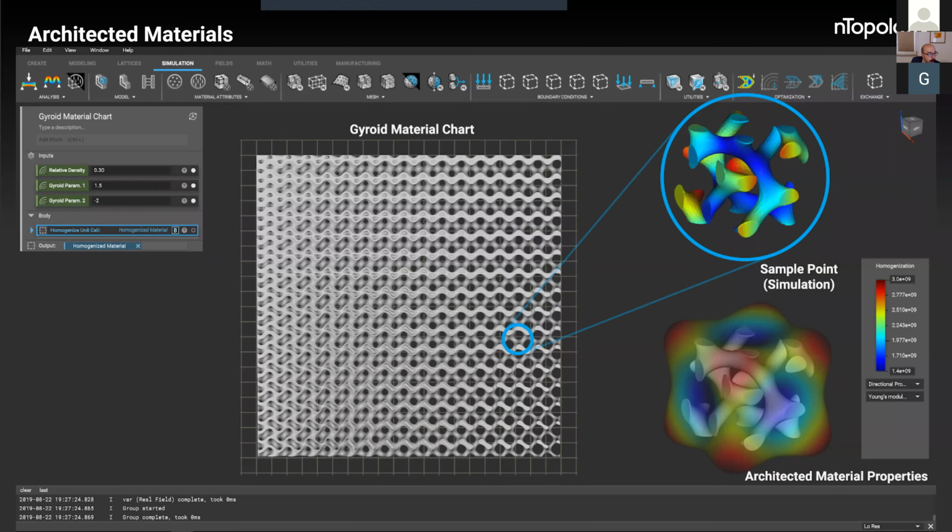All right, can the lattice structures also be exported in step format for further native CAD editing? Good question. So I would recommend exporting out lattice structures in 3MF file format rather than a step file format, right? If we think about traditional BREP-based modeling tools, there's a reason that you typically can't create BREP lattices. I've heard from a lot of folks, they've tried to create gyroid structures and things like this, and they've spent weeks and months trying to do that. It's all about using the best tool for the application. And so in this case, I wouldn't recommend exporting out a really complex lattice structure as a step, although you could do that. I'd recommend going out with something like the 3MF because it's going to be easier to then go ahead and manufacture that data afterwards.